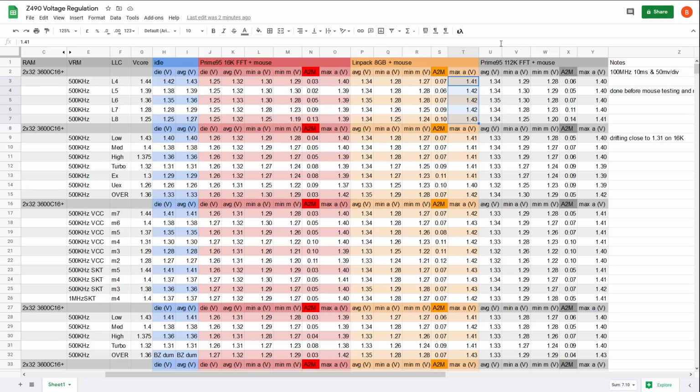In that scenario, we might start approaching the 1.6 volts level on the LinPack runs, but even then, that's not super concerning because that's what, 150 millivolts more. So this would be like 1.66. There would also be slightly more current going into the CPU, so it might end up being more like 1.68. Wait, no, 1.58, right? So as long as it's somewhere around 1.6, I'm not concerned with the maximum voltage level.